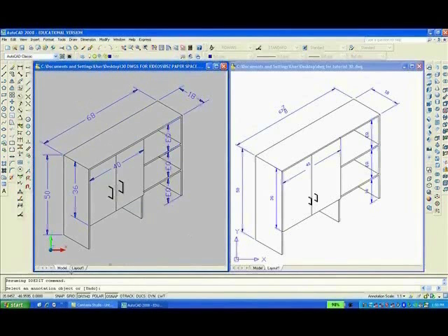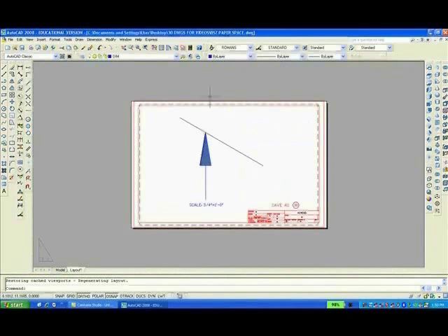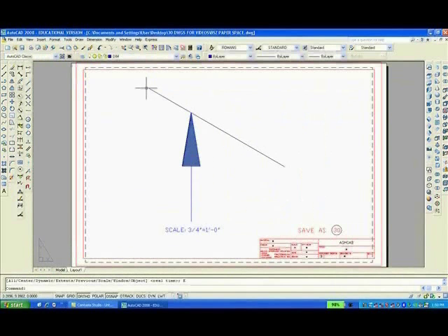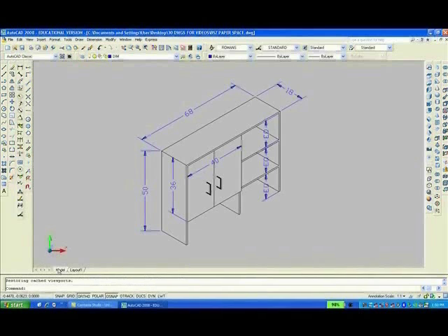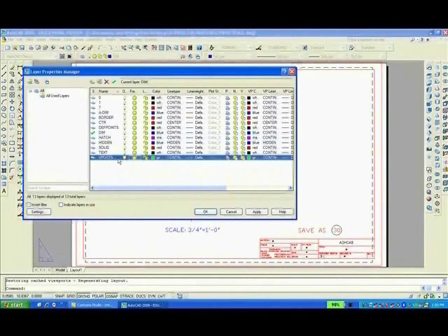So I guess I'll go into layout mode now, and I'll go into making the whole drawing fill a screen. I'm not quite sure why that is showing yet, but I'll want to Z, enter, E, enter. Oh, I know why. It's because it's already in model space, so I have to fix that. I'll go into model space now. Now if I go into paper space, well, it still doesn't show. Shows. All right, so I'm going to make layer, viewports. Oh, it's off. That's why it happened. All right, make that current.